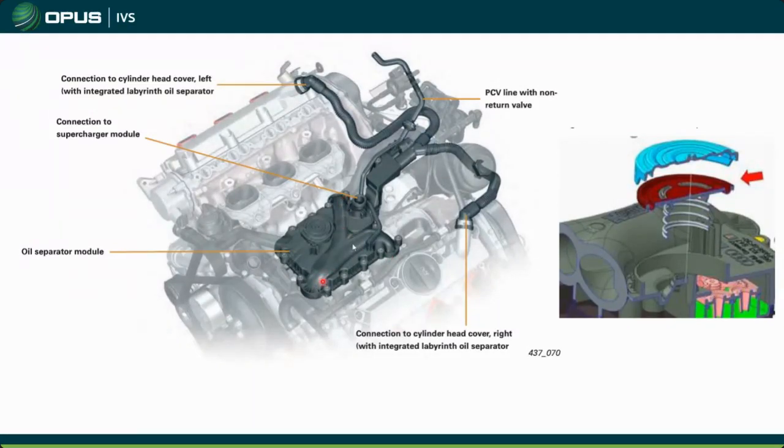So when you remove this, there's going to be coolant in there. What I always did was use my oil extractor, and I would just kind of shove it down here in the corner. And as I loosened this thing up, I tried really hard not to pull it all up at once and drop all the coolant out. I would just let it out slowly and suck up all the coolant, because once you're in here, you really don't want your coolant and your oil to mix. Obviously, that's not good.